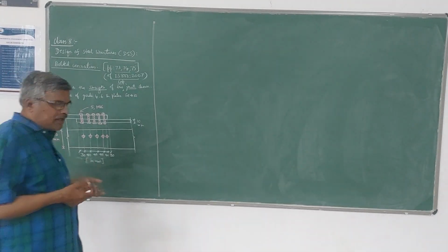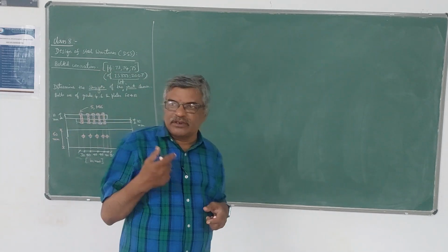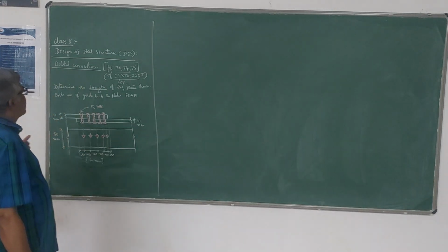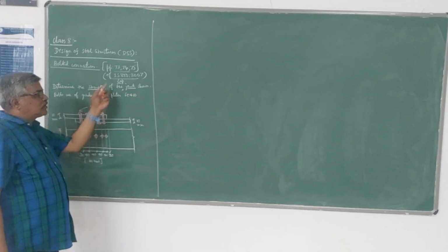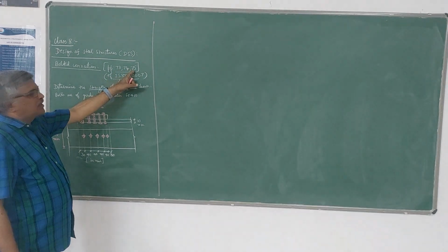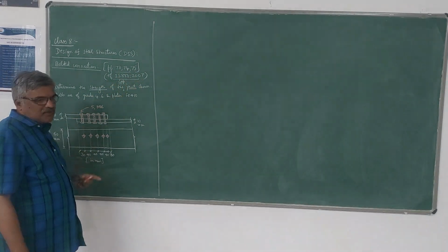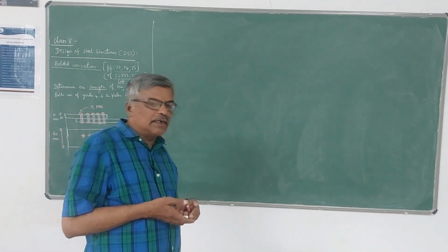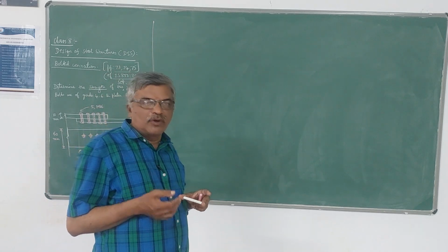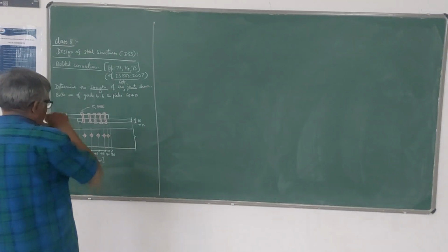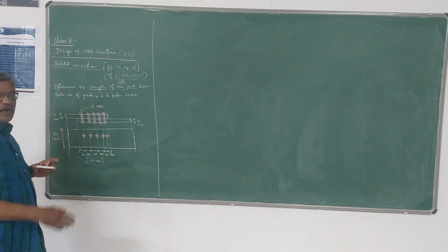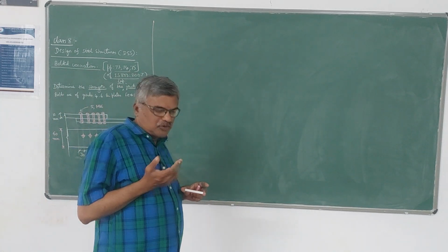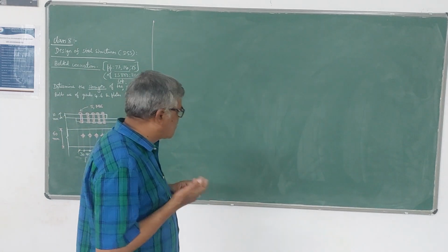So mainly in steel design, we deal with two types of connections, bolted and welded connections. Here, for bolted connections, we can refer to page numbers 73, 74, 75, etc. of the IS 800 2007. Now I will discuss how to design a simple bolted connection as well as a simple bolted eccentric connection, and what are the total provisions that are required, equations we are going to use, how to find the design strength of a joint or efficiency of a joint, all those things.